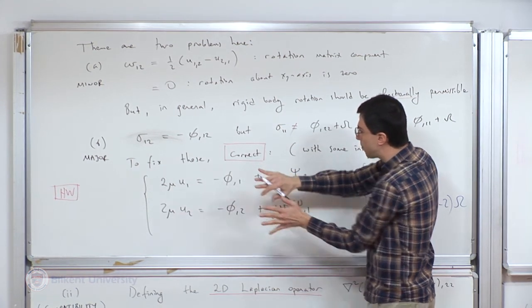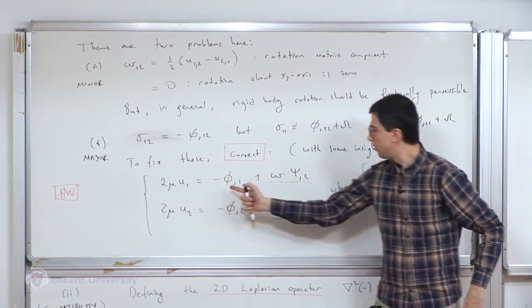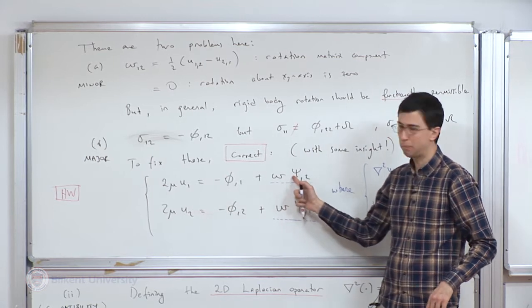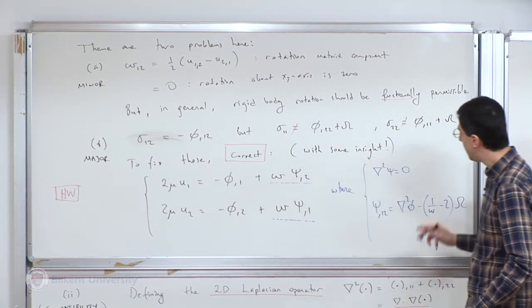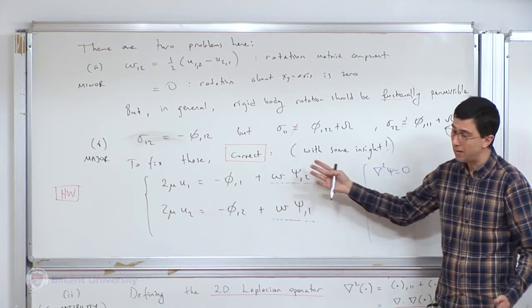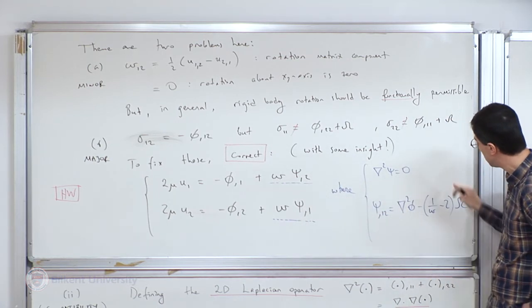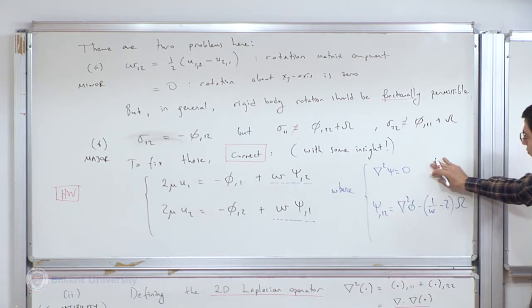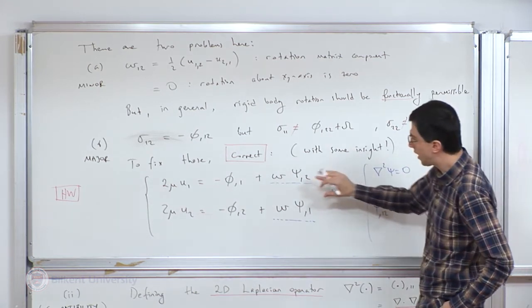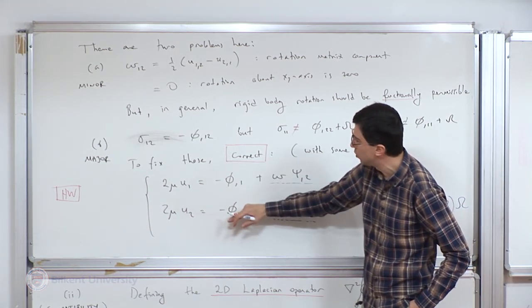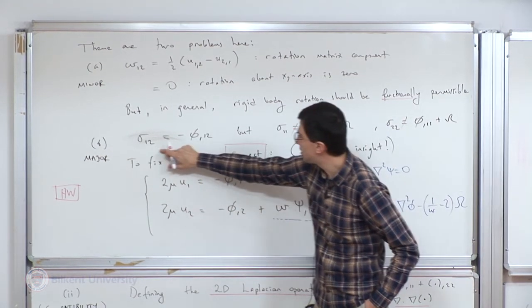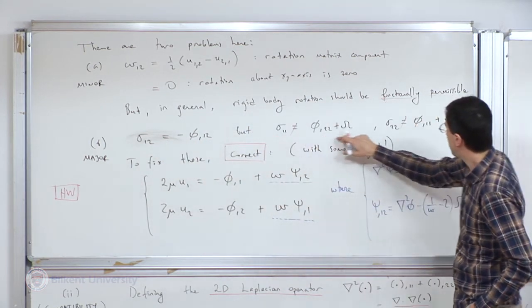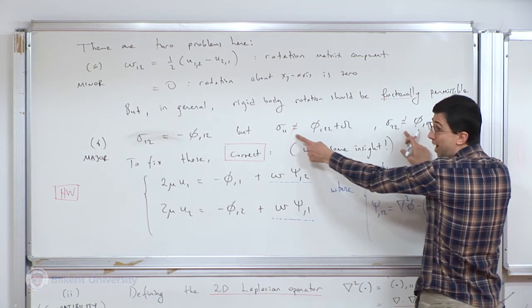And now to fix that, I'm throwing in another term. This function phi is the Airy stress function. It has a name. This function psi, no name function. But the function cannot be anything either. It is subject to these two restrictions. And it turns out these two restrictions are needed for two reasons. First of all, I need to make sure that with this U1 and U2, I need consistency with this proposal for the shear stress, and also for the normal stresses, these two equalities have to hold.